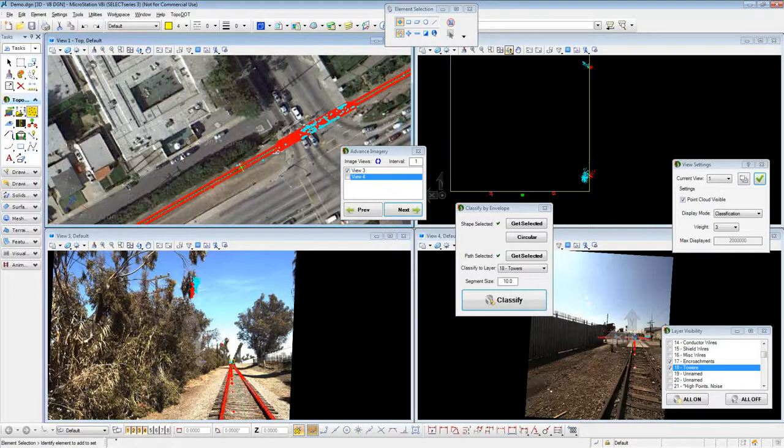Okay. So I think what we're talking about now, I've got some ideas in the back of my head. If you laid lines, if they were like alignments, and you actually offset them, and they were at the right elevations, you could break this up into smaller pieces and smaller triangles or smaller rows, so to speak, and it would follow those. The 2-dimensional tilt wouldn't matter as much. Say if you did it every foot, it would probably still be faster. But you would have to define where the surface of the road should be and where the rebar is. Those alignments would have to be defined by you.